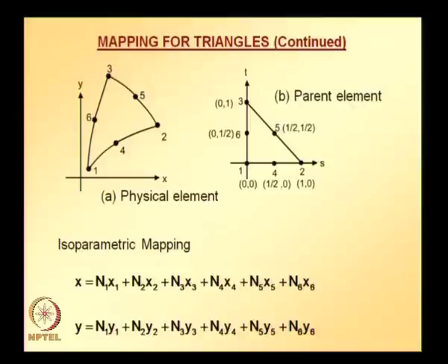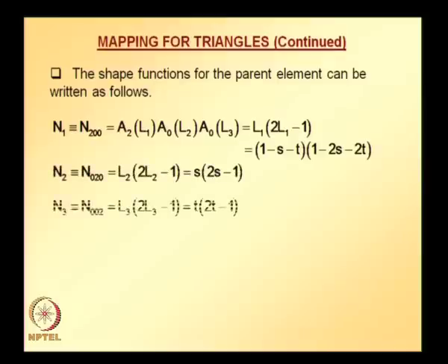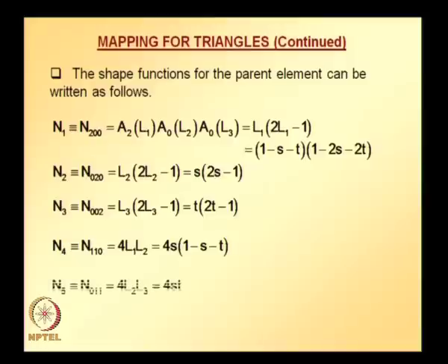For the 6 node element, we already saw earlier in today's class the shape function expressions for N1 to N6 in terms of L1, L2, L3, and L1, L2, L3 we already have. So, using that information we can write shape functions for all the nodes N1 to N6.